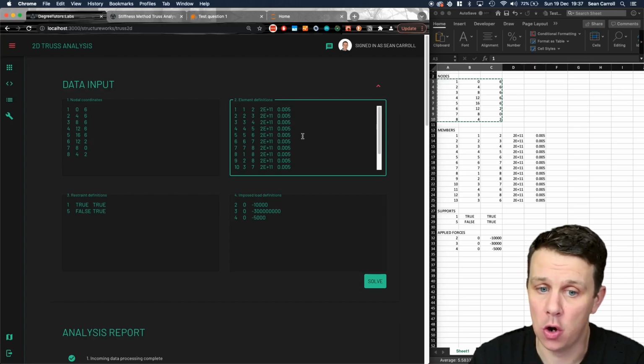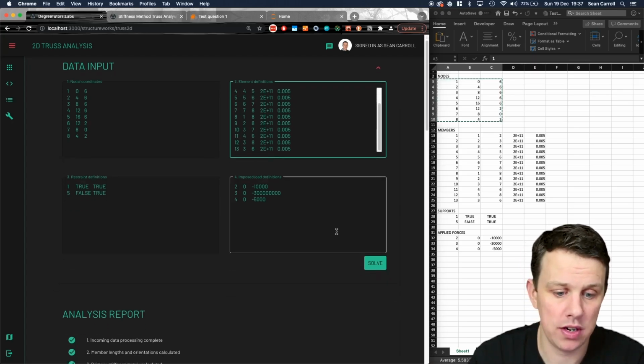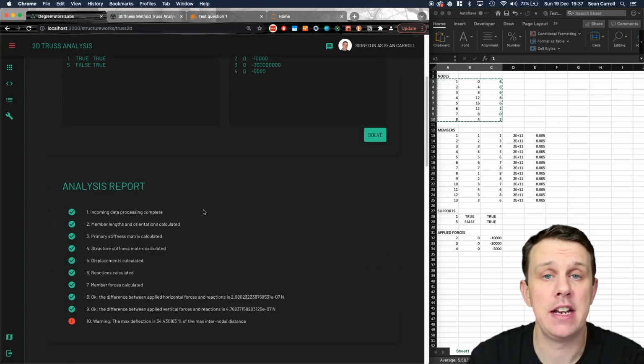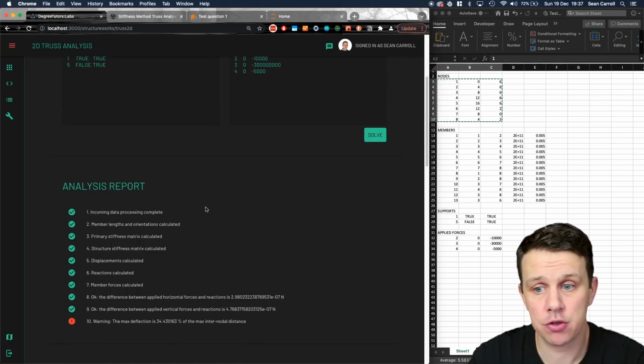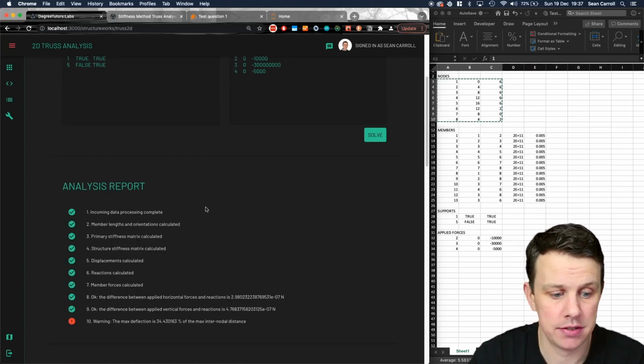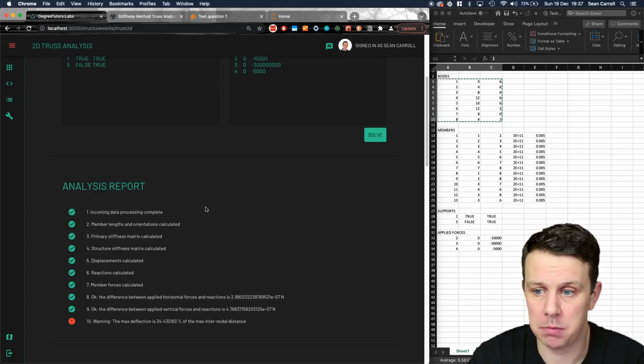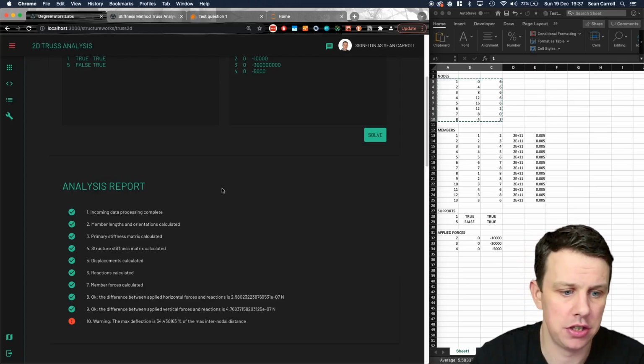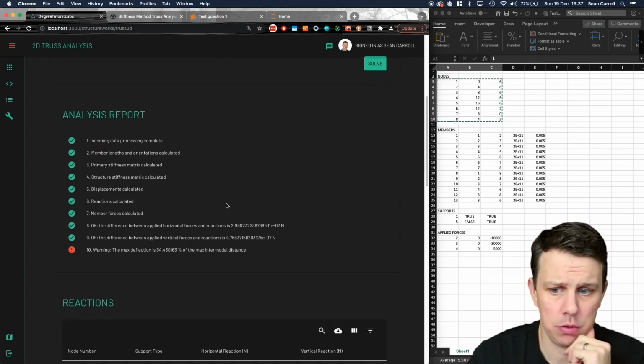And so you're going to want to know pretty quickly, and I'll raise another warning down here in the analysis report, if any of the members in your structure exceeded their yield stress. So that'll be a flag for you to go back and check and make sure you're okay with that as the engineer. All right, that's the analysis report.